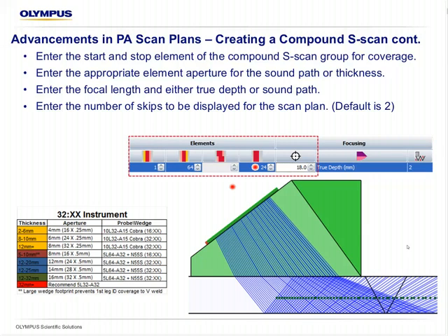Now, even though there's just a slight couple millimeters difference between some of these configurations, there is a benefit for coverage versus appropriate aperture versus ability to calibrate and provide a good inspection. The example we're going to use in a couple of the data files and in our SUB is a 24 element aperture using 0.5 millimeter pitch, which results in an overall aperture of 12 millimeters, which is a very common probe for the typical 12 to 20 millimeter thickness range.